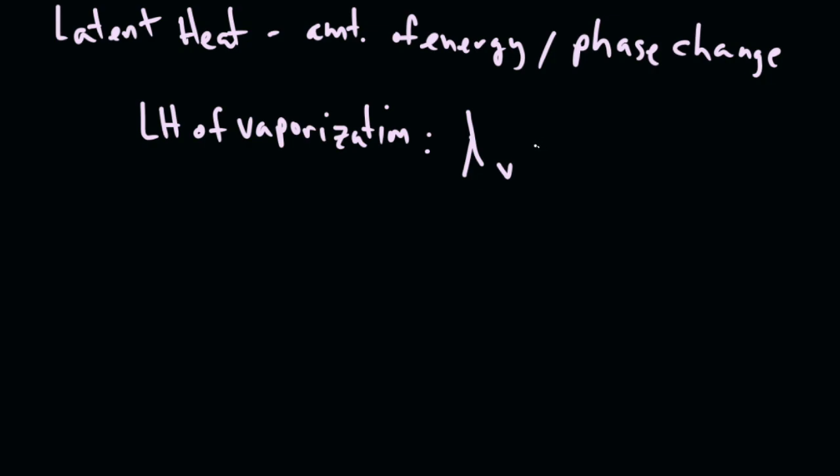What we typically do is leave it as an enthalpy, and we don't have a subscript v. We actually use those f's and g's together, because it's the energy associated with vaporizing, going from liquid to a gas, and we would use this symbol here. There's also a latent heat of going from a liquid to a solid. We don't call it solidification; we call it fusion.